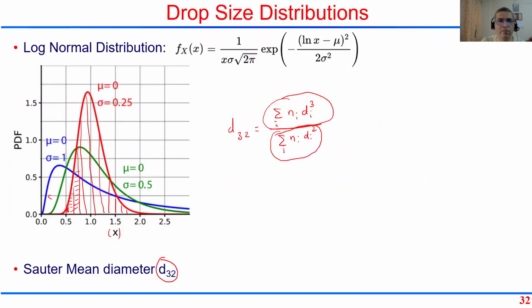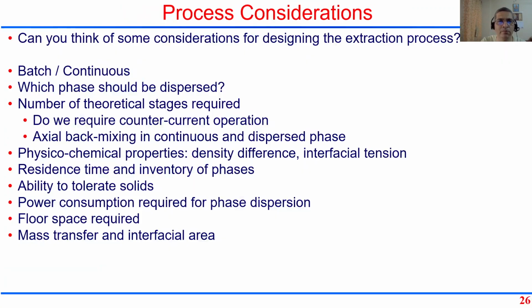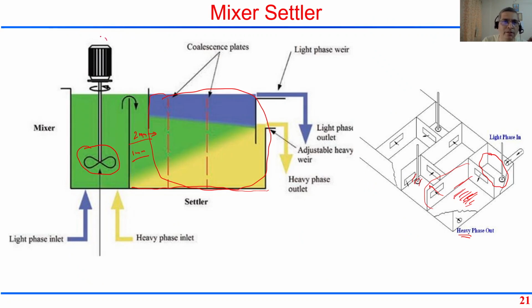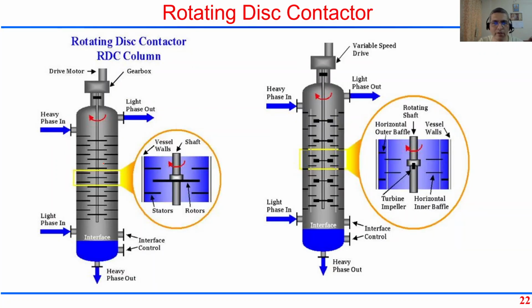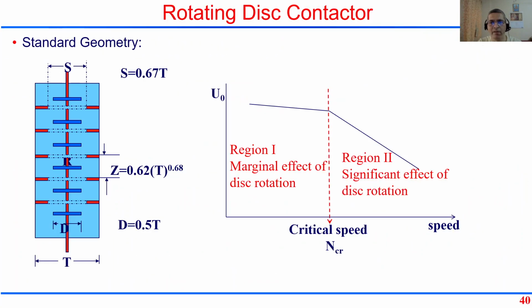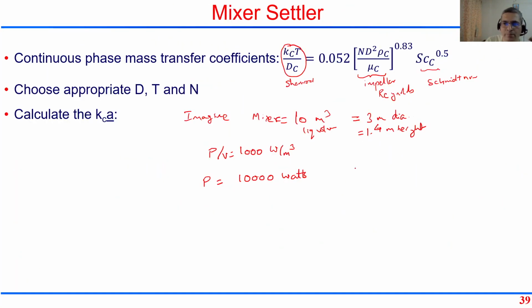Where did our picture go? Our picture is way back. Okay, this motor is giving the power, right? The agitator is dissipating that much amount of power into the liquid. So we can all relate it to the diameter of the impeller, and this power has to come from the impeller: power number times rho n cube and d raised to 5.